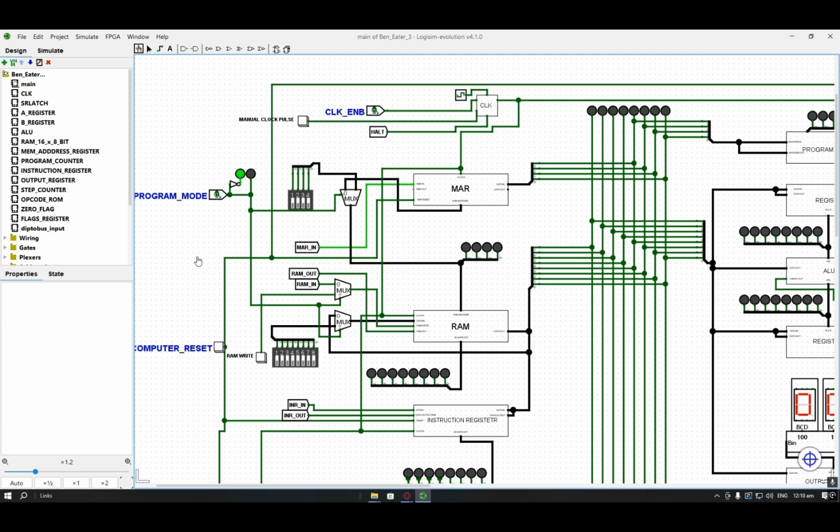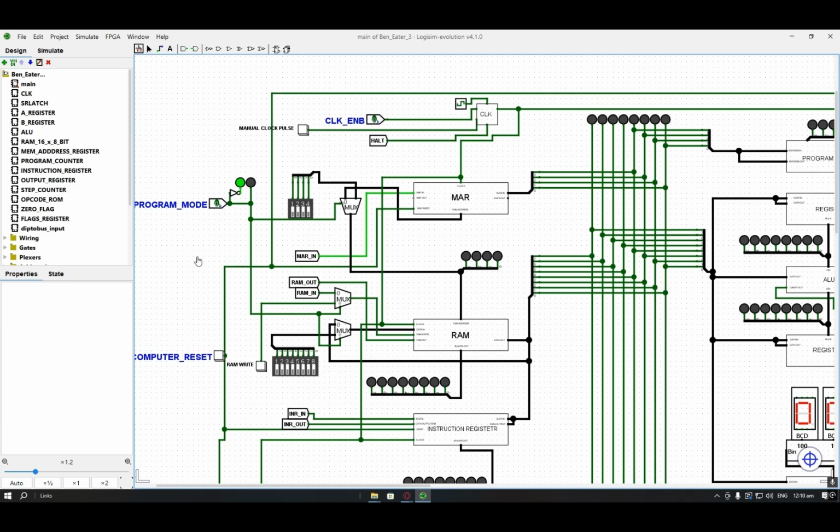So, the most critical operation in the memory system is the store accumulator instruction, or STA. During STA execution, the accumulator places its value into the bus, and the RAM writes this value into the address currently stored in the MAR.